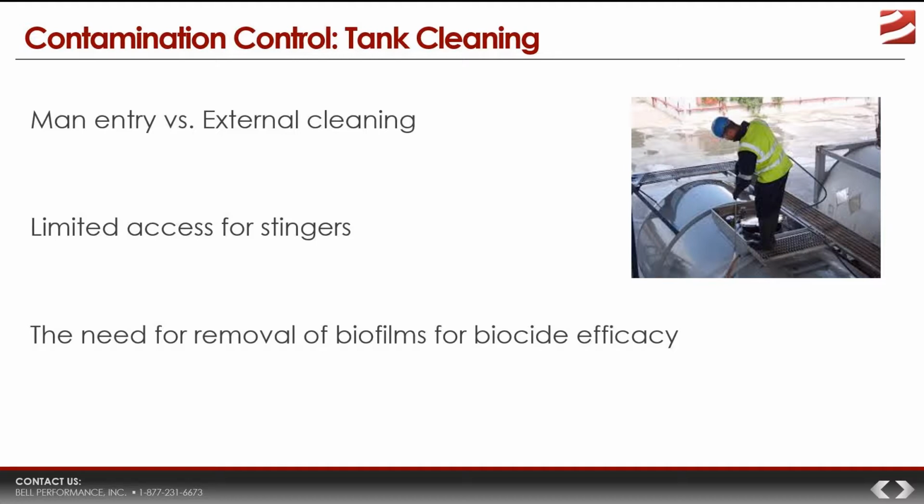We do the best we can with what we call external tank cleaning. Basically, tank cleaning from the outside, where you've got a suction system and you're using stingers and vacuum hoses and things, and you're trying to suction out as much of the biofilm and as much of the water out of the tank as possible.